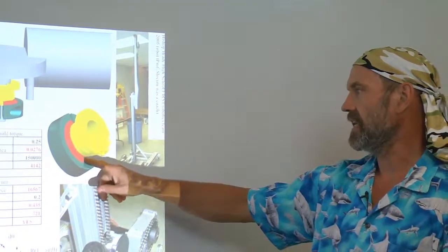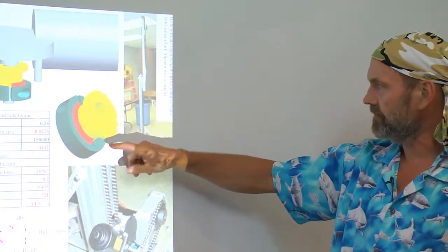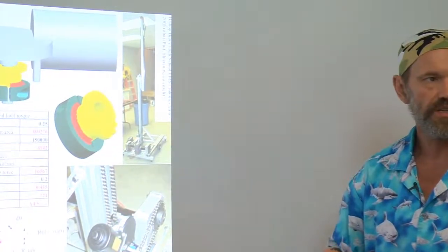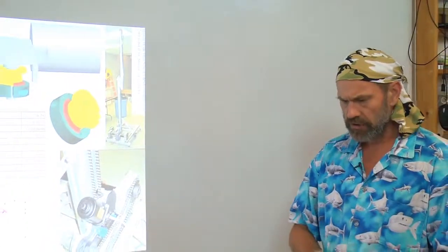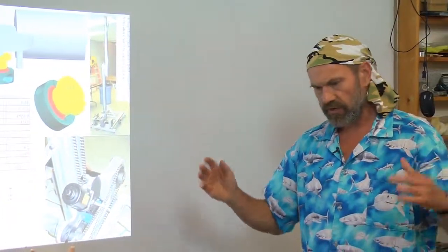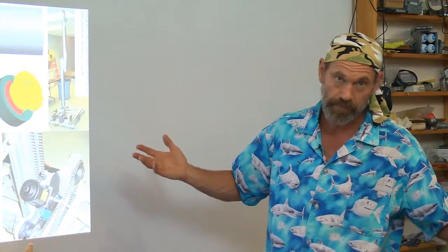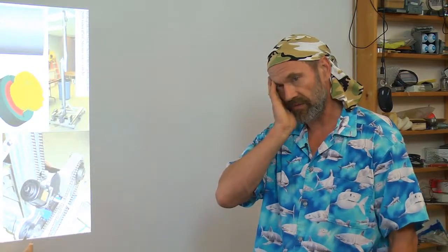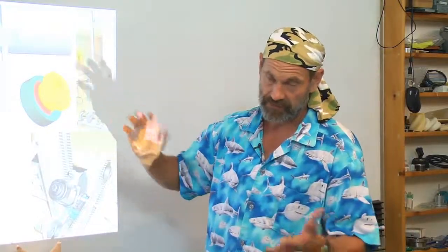So now you have an asymmetric weld with the radial load from the chain force. Is there enough strength in that weld to handle that chain force? You could say, design it in solid modeling, run your finite element analysis, and see if it works. And it may work. But if it doesn't work, then you have to think, oh wow, what do I have to change? This is where the value of real engineering happens. You do the closed form analysis to write the equations and then implement them on the spreadsheet or MATLAB, what have you.